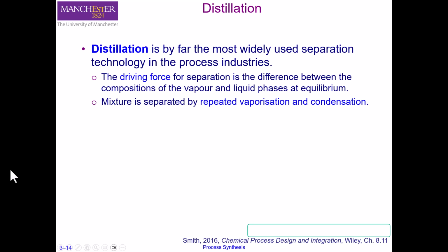Distillation is a very important separation technology in the process industry. When we decide on a separation unit in our process, we normally look at the economics of the separation unit, the volume to process as a feed, and the throughput of the unit, and then finally we look at the recovery and purity of the system, the purity of the product. Another important factor is the reliability of the technology, and distillation is one of the very old technologies, so there has been a lot of investigation into the design of distillation columns. This technology is much more reliable compared to new technologies like membrane technology.